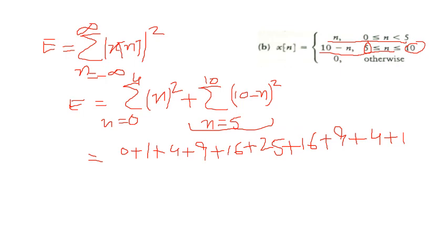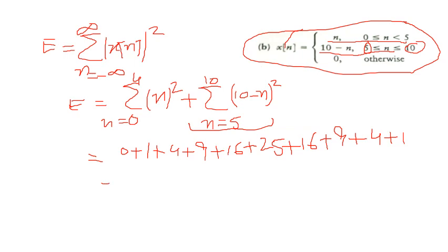So it looks like it will give you some finite energy, because we already know this is an aperiodic signal. So aperiodic signals are normally energy signals, right? So its power will be 0, because for the power formula, we have the limit as the period tends to infinity. So when I divide this finite value by infinity, I should get 0, right?